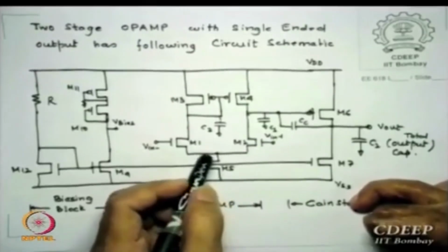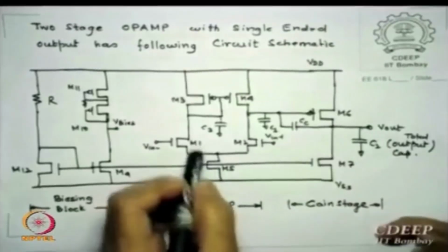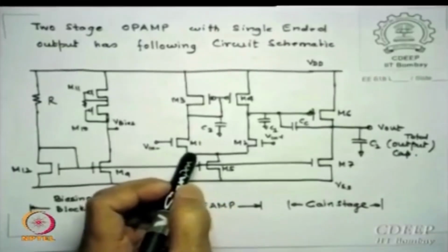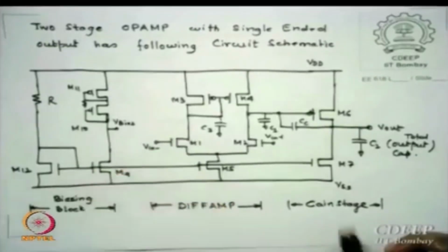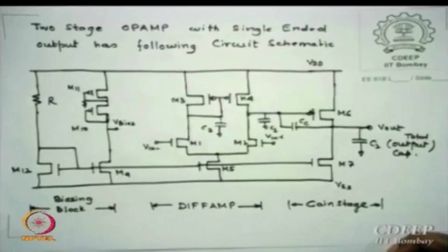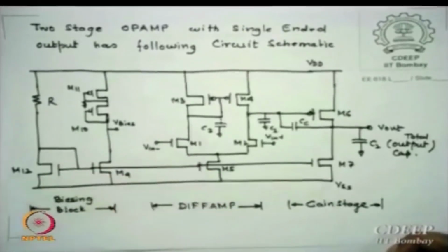So I actually now see to it that that drop is the maximum available to you. So I also accordingly put VTN, because it will be subtracted out of this. Please remember VGS minus VT is VDS. So if I have to subtract out of it, I should choose the minimum value of VT so that that is the highest drop across which it will come, so that still it will satisfy your 2 volt requirement.